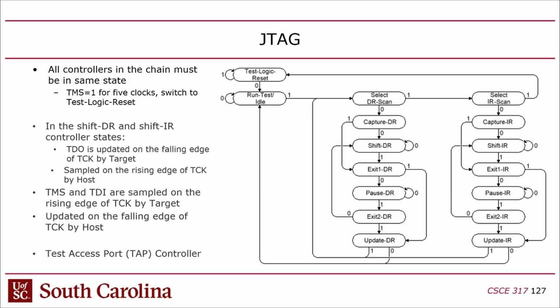Now, not from the Linux machine. From the Linux machine, it's actually going over USB. Once it gets to the FPGA side, it goes into the USB Blaster, and from the USB Blaster it becomes JTAG. So you're using JTAG, but if you look at the cable, it's not a JTAG cable. We use the USB cable. Okay, that's all I got.